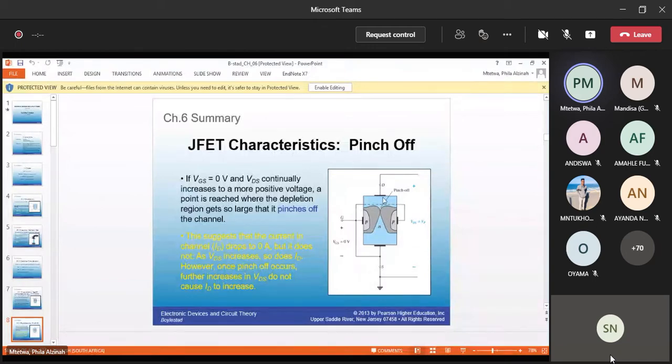Yet we have enough on the source, and the drain is made positive enough to attract the electrons, but there's an obstruction here, and that speaks to pinch-off voltage. It's important that you understand that, because it's one of the parameters you are given when talking about field effect transistors. Pinch-off voltage gets specified. That's the voltage at which your output is shut off, with everything else being connected.